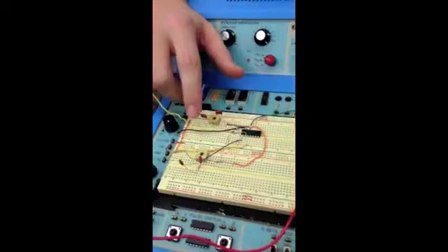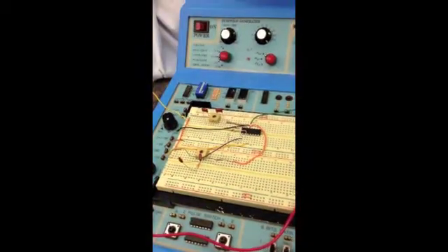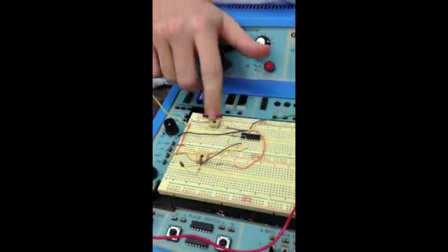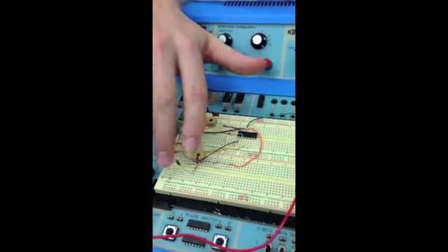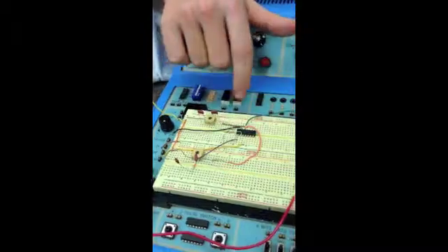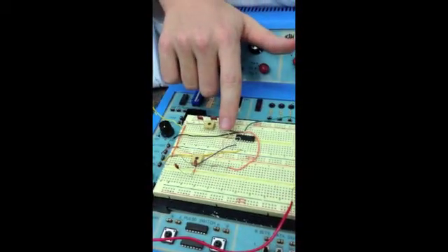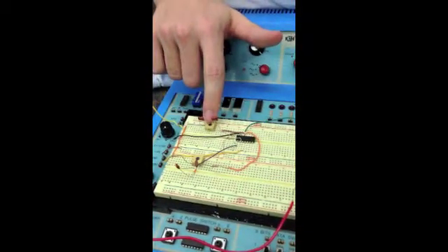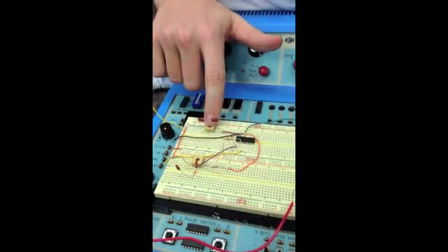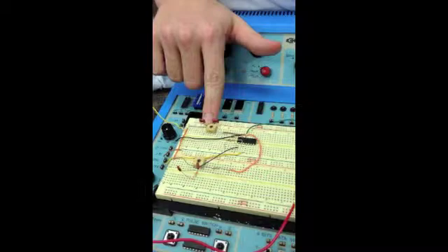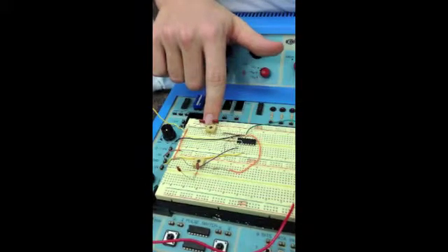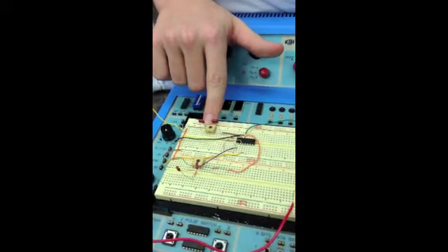In building this circuit, we used some trial and error and some game time adjustments to change the values of these capacitors, as well as R5. We ended up decreasing R5 and tried many different values for these capacitors, C3 and C4. First trying larger ones, then smaller, and settling on a value of 27 nanofarads.